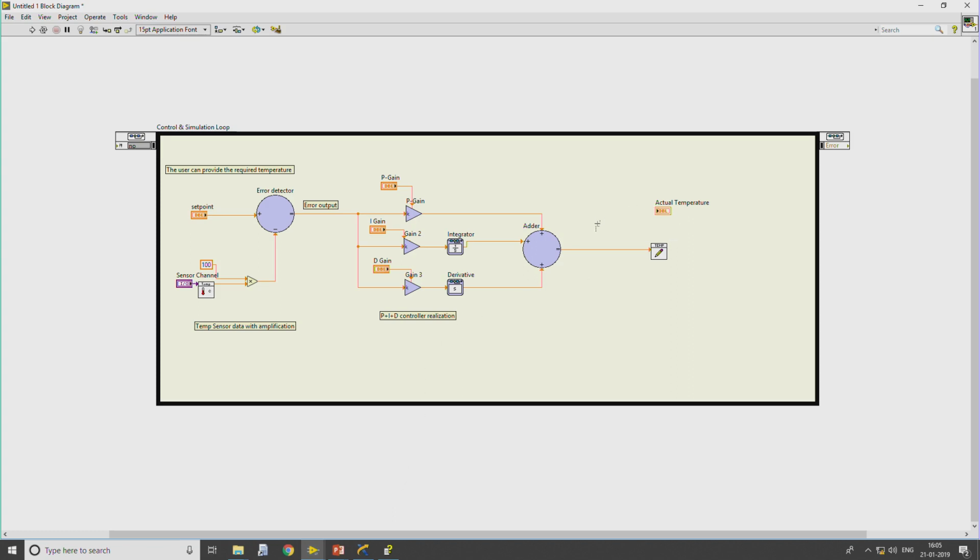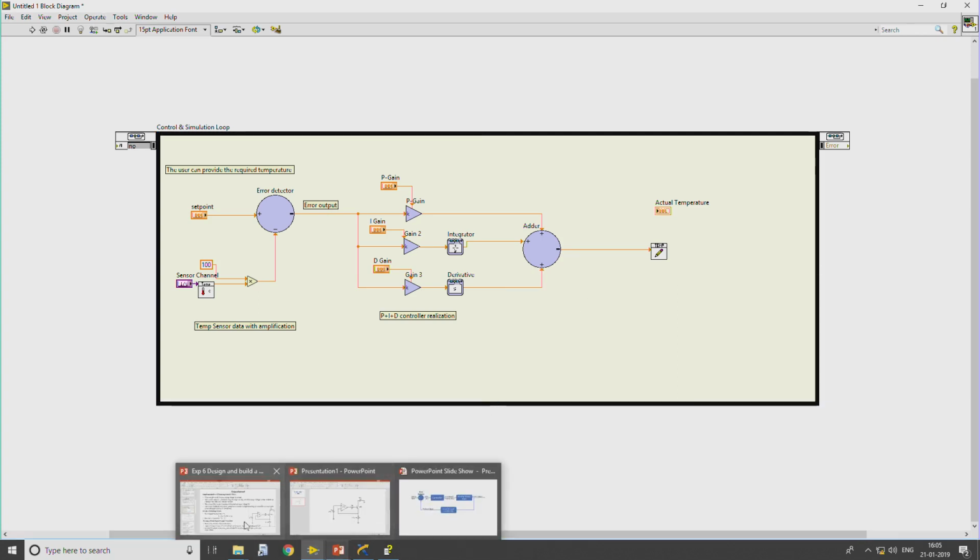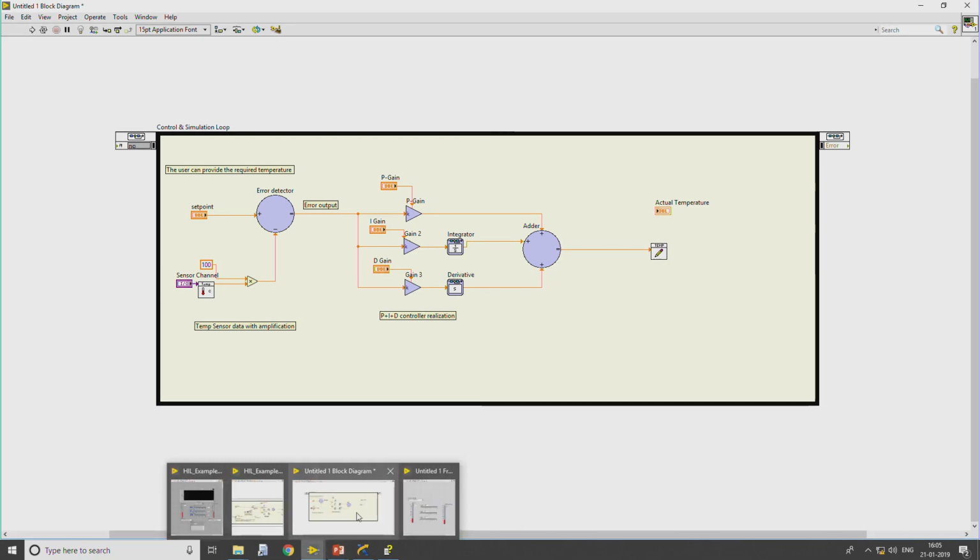So, by creating some logical icons here, logic saying that if the input voltage is greater than 1 volt, pass the maximum voltage here, such that the generated output voltage will not be greater than 1 volt, and both the driver circuit as well as the plant and the data acquisition device will be in a safe zone. So, let me add all the required components.